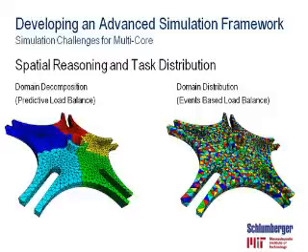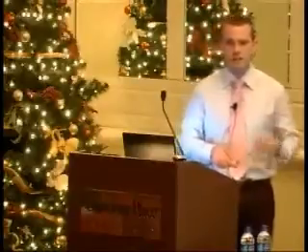So with respect to spatial reasoning, in a conventional cross-machine type application, you'd be dealing with something called domain decomposition, which is effectively, if you've got, in this case, 5 machines, you want to break up the model that you have into 5 distinct parts, send it out to each of the machines, they would process and then coordinate and whatnot. Now, important to remember, you have to have communication between the domains because of the actual calculation. And also, when you choose the size and shape of these domains, generally they're chosen as to being almost exactly the same computational expense, such that you're doing what's called a predictive load balancing. You're assuming each processor is going to take the same amount of time for the same job.